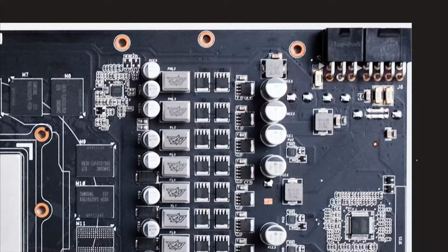And the low side MOSFET is, as I've already talked about, because it has to handle 10 times the current, it will produce 10 times more heat for the same RDS on. That is also why you will often see on this specific card, if I remember correctly, the low side MOSFETs have 3.68 milliohms, which is actually quite a lot for low side MOSFETs, and then the high sides have like 4.5 milliohms or something. So you will pretty much always see that the high side MOSFET has a higher RDS on resistance than the low side MOSFETs, which is because they have to handle more current.